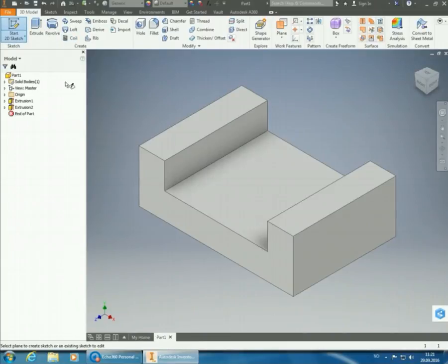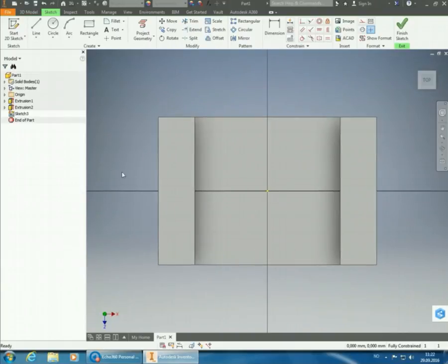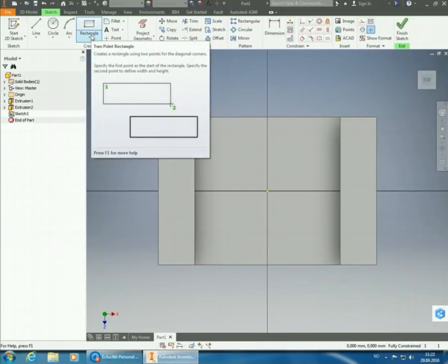I'm going to start a new sketch, and I'm going to place it in the middle here on the parts. Alternatively, it could have been done in the very first sketch we did. We could have chosen to put the slot and the holes in there and just extrude around them. But now we get to do an extrude where we're actually cutting, so we get to show that. I'm going to tilt it to get it the right way around. And then I'll place the slot first, and then we actually go to the rectangle part.